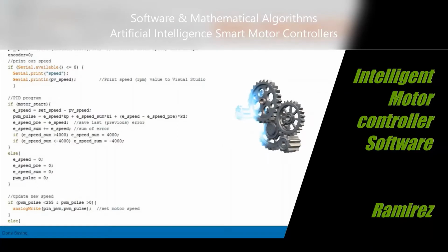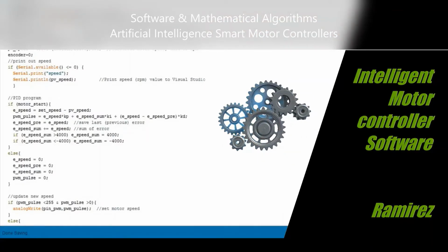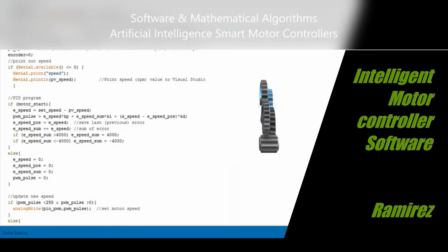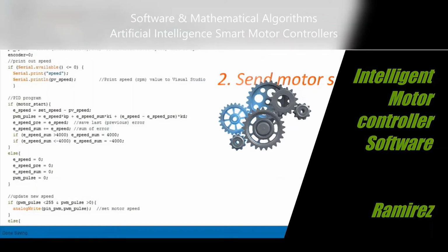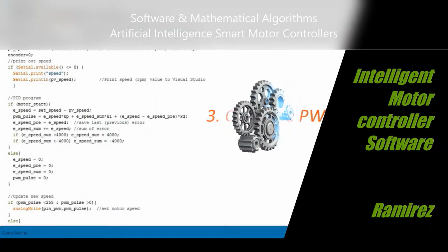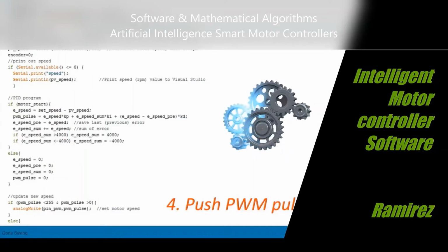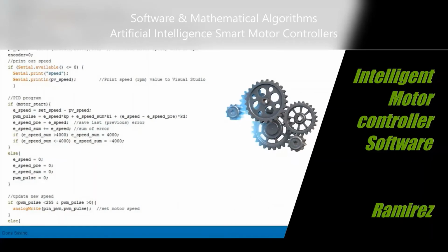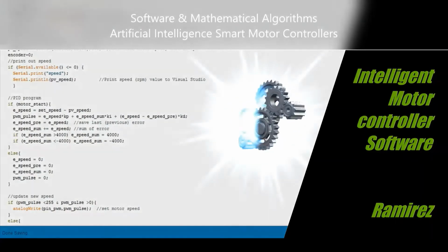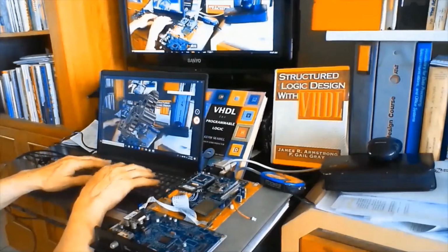The duty cycle describes the amount of time the signal is in a high on state as a percentage of the total time it takes to complete one cycle. The frequency determines how fast the pulse width modulation completes a cycle, and therefore how fast it switches between high and low states.